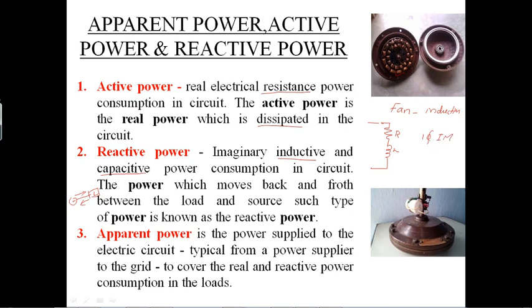For the fan to keep running, we have to give power. So what is induction? I have explained already. If you change the flux in a coil, we'll be able to get an EMF induced in the second coil, right? Faraday's law states that. So here also the induction process is going on. An inductor should be there, because only then will the induction action occur, and only then will the electrical power get converted into mechanical rotating power. For that induction to happen, that inductor coil is very much essential, right? And as we can't make a pure inductor, there will be a combination of resistance also.